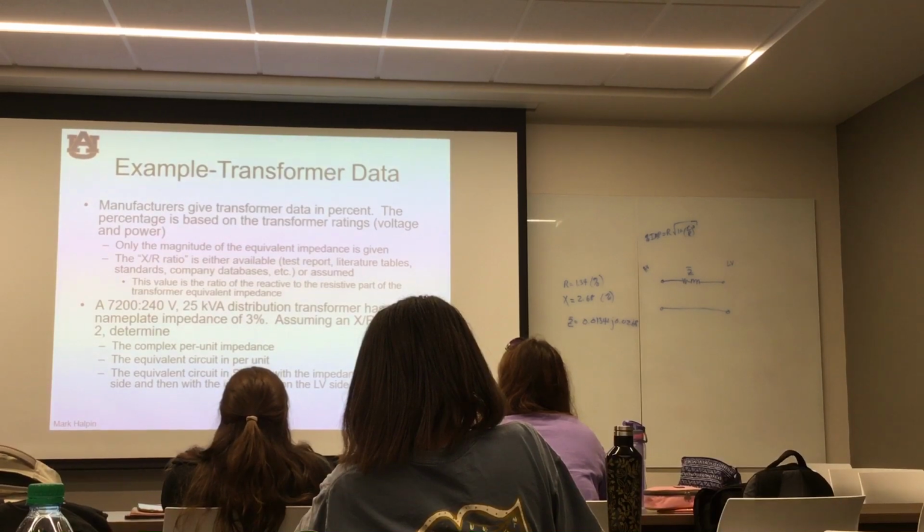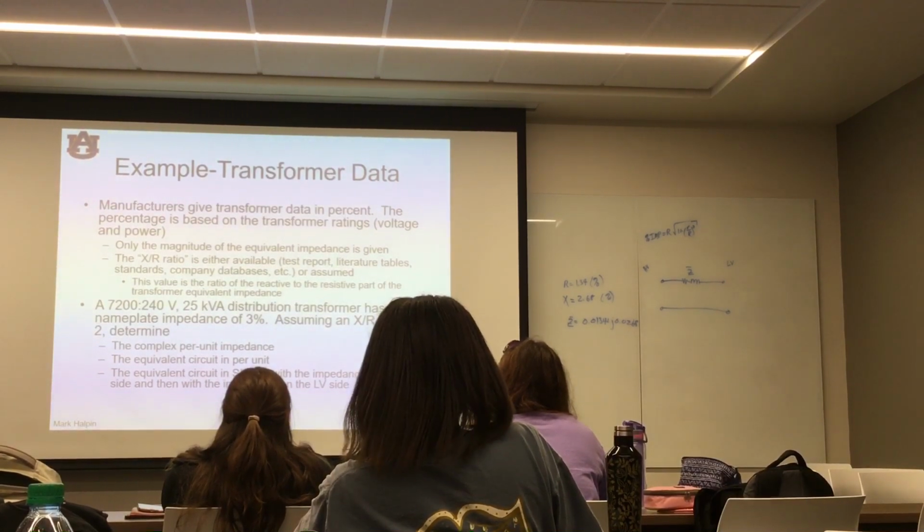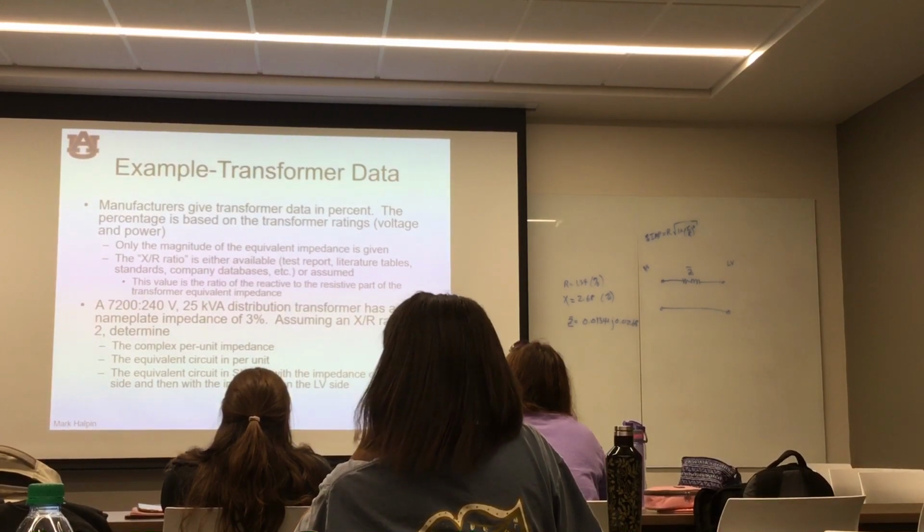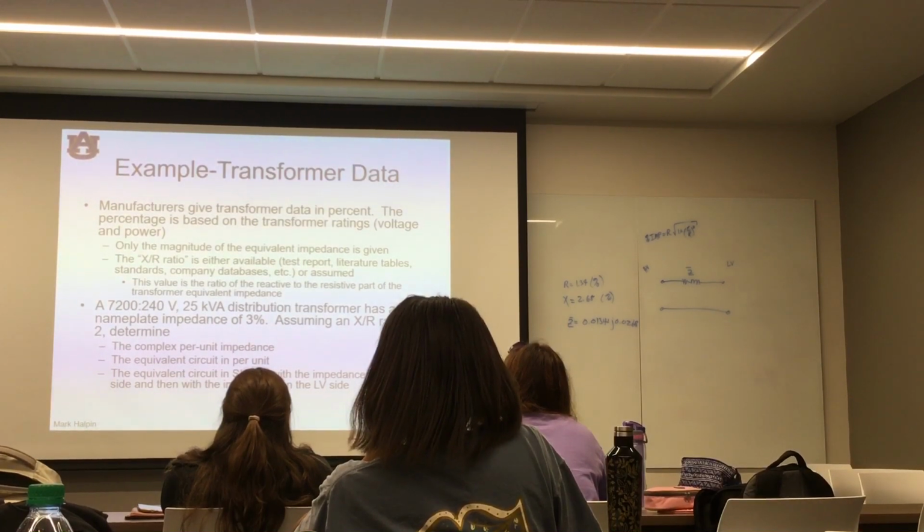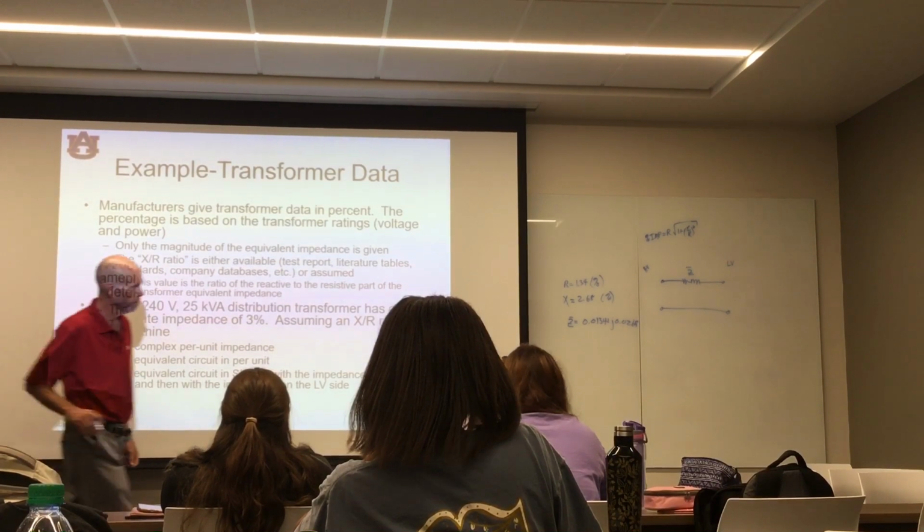So how is it we have 1? Well, in per unit, when this goes to a straight line, I have some impedance over here and some impedance over there, and they're in series. I just add them up and I get 1, like we drew over there. So really, the ideal transformer sits right here. But because this is in series and we add them up, the manufacturer only gives us 1% impedance, not 2. Because I add them up, I have to decide whether to put the ideal transformer on the left or the right. That's our issue here.